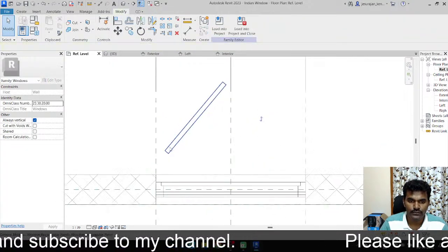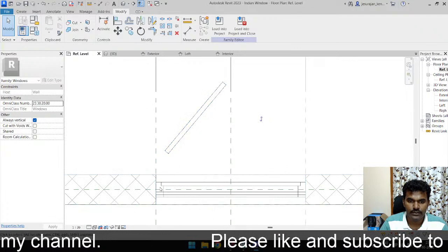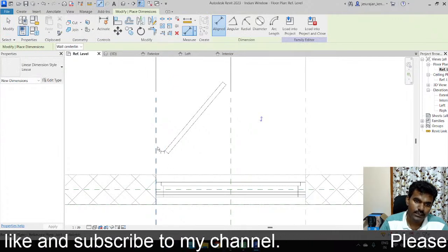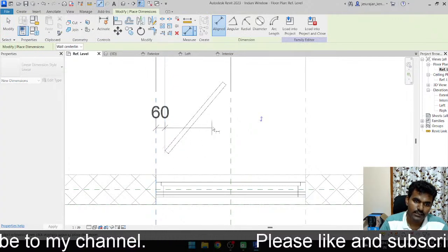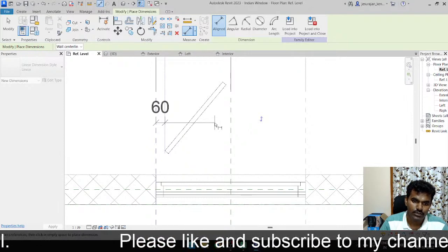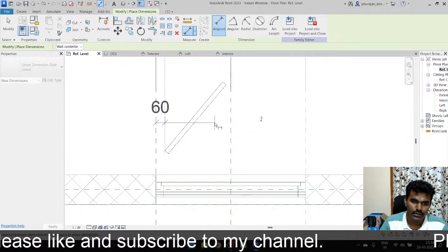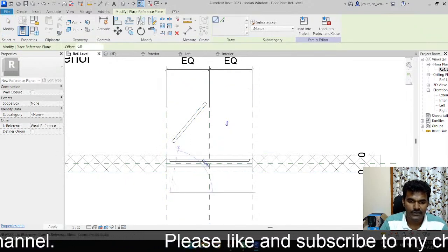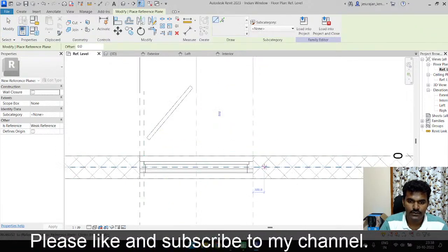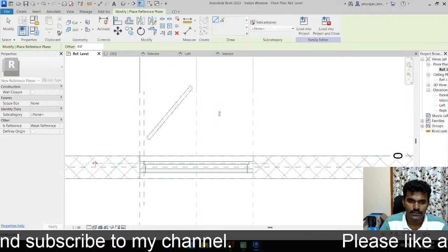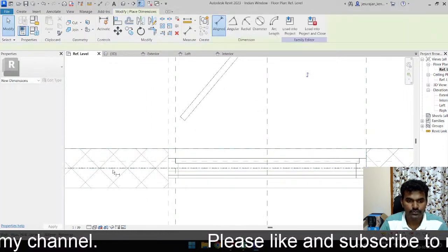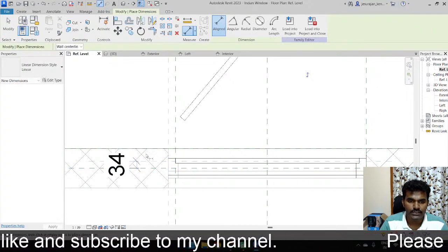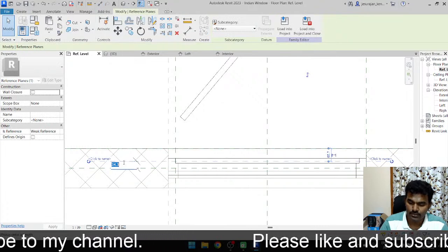Now I have to fix this frame with the window. Okay, just go to DI. I can give a dimension also. Otherwise, I can draw a reference plane and I can align. Just draw a reference line. So for now, I'm not creating any dimensions or parameters here.